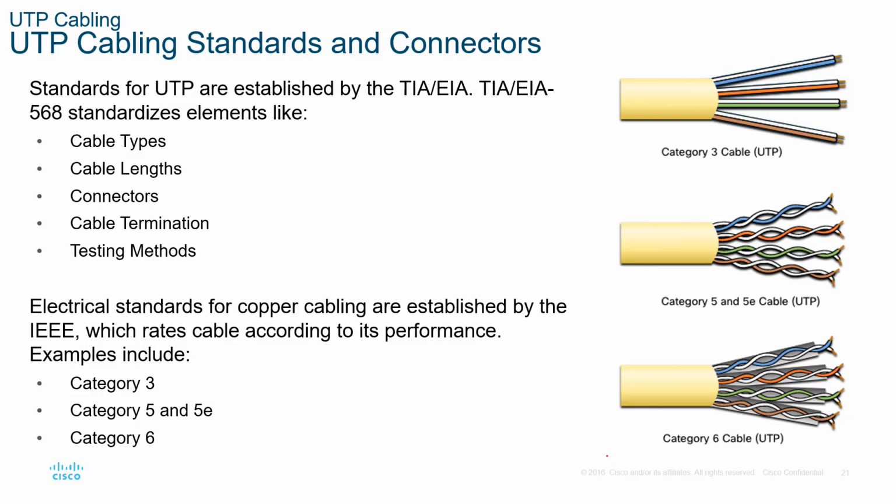Cat6 is becoming the new standard for our data installations. Cat6 allows for higher speeds of data, and Cat6 could also include forms of protection on individual pairs. It also is made out of better material, pure copper, and allows for a higher frequency of data transfer, thus allowing for more bits per second. Hence why Cat6 is better than Cat5e.